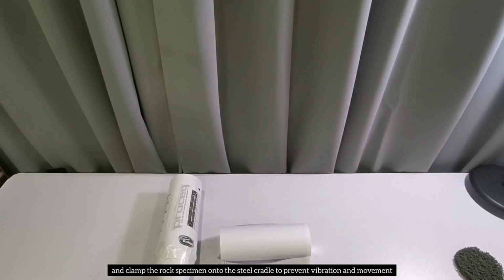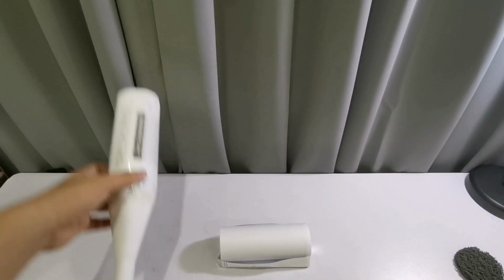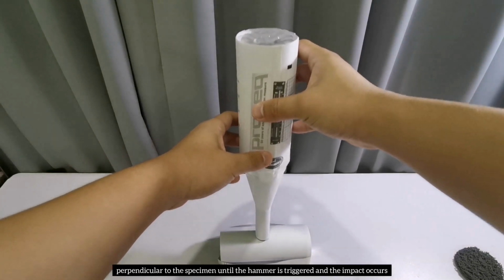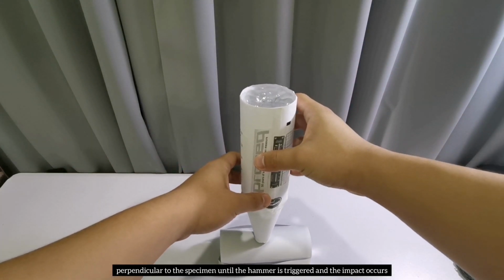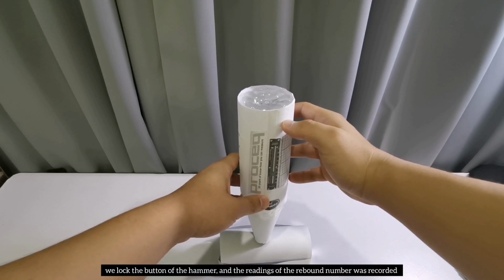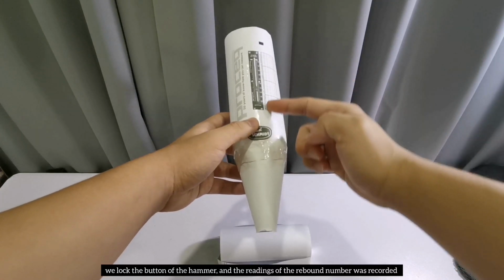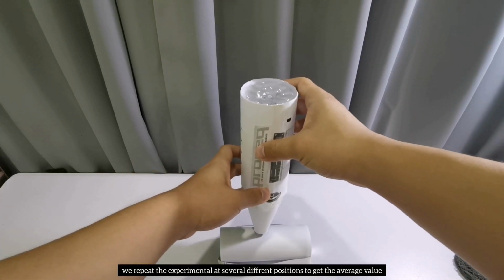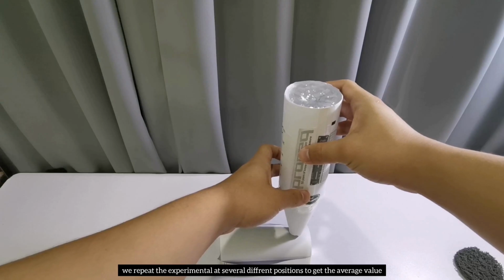prevent vibration and movement. Next, we compress the hammer spring by depressing the plunger perpendicular to the specimen until the hammer is triggered and the impact occurs. We lock the button of the hammer and the reading of the rebound number is recorded. We repeat the experiment at several different positions to get the average value.